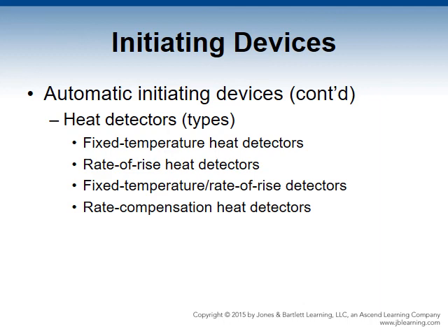Fixed temperature rate-of-rise heat detectors combine the operational characteristics of two into one. Whether a fire develops slowly or quickly, the detector can detect it and send a signal to the fire alarm panel. If the fixed temperature portion activates, the detector must be replaced.